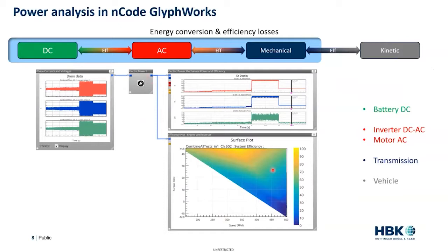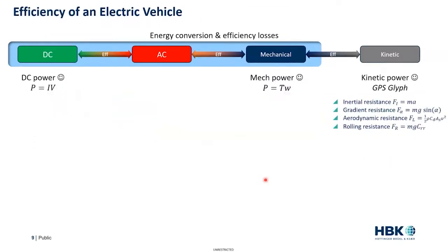We can play what-if games, and we can try and quantify and improve our inverter to get better efficiency out of it, diagnose problems and troubleshooting and things like that. So this is the key thing, and obviously the efficiency maps are what we're seeing. So how do we calculate that efficiency then? Well, the efficiency is all based on calculating power, so instantaneous power, and then sort of averaging it, if you like, to find the energy.